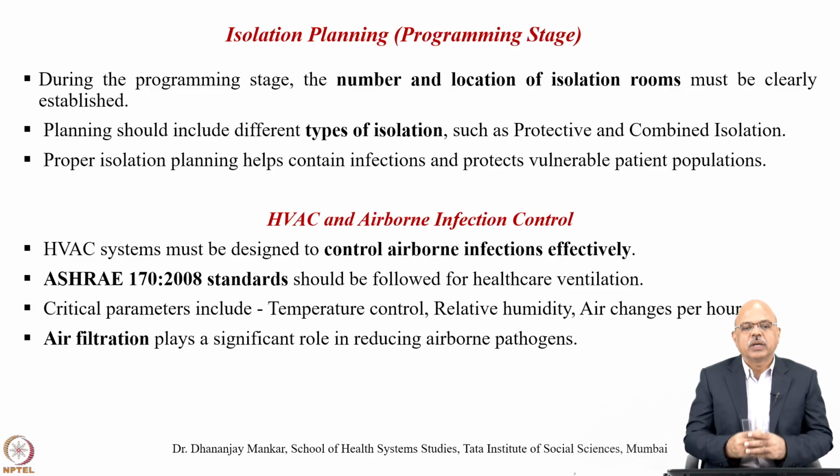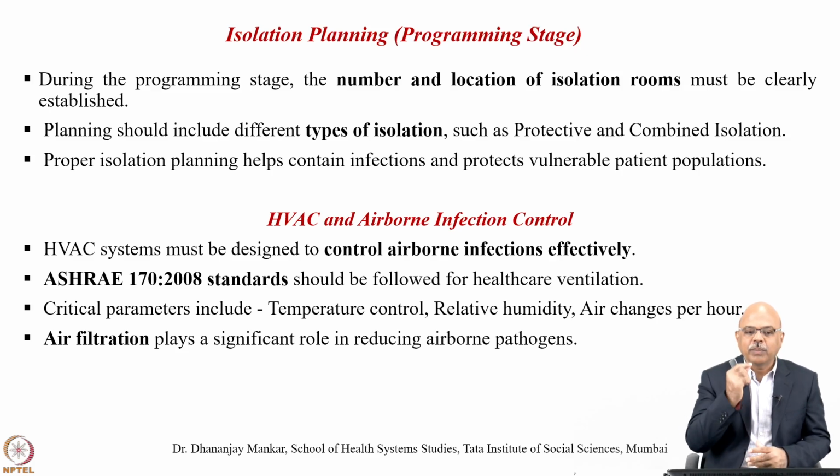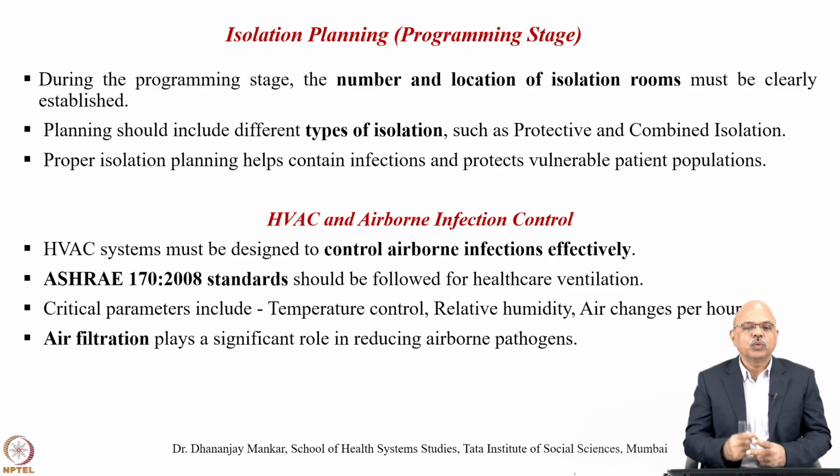The ASHRAE 170-2008 standard should be followed for healthcare ventilation. The clinical parameters include temperature control, relative humidity, and air changes per hour. Air filtration plays a significant role in reducing airborne pathogens, which are very important and sometimes very difficult to tackle.